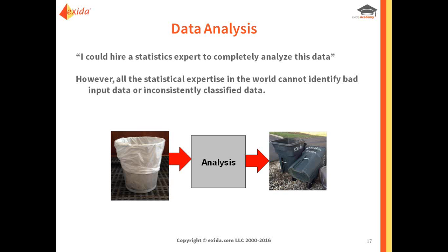A good field failure data collection program has a number of important attributes. It specifies a site inventory database, and it can include the product manufacturer, the model number, the serial number, the design version level, the product classification, the installation site, failure event records, and proof test records that include dates, methods, and results. You can have all kinds of calibration information. So when you get a failure, you list all this information. It might take a little bit more work, but it's not an excessive amount of work.